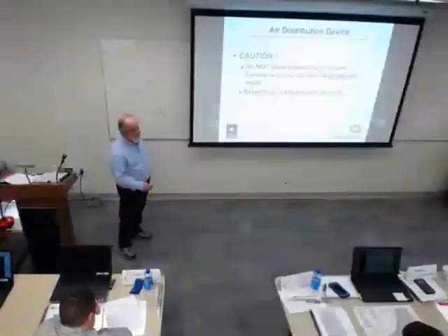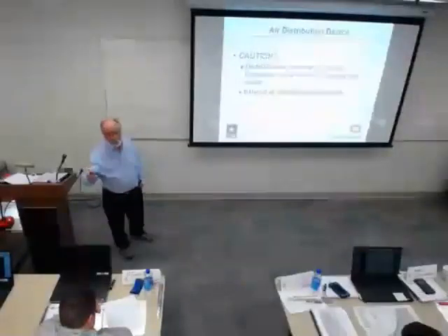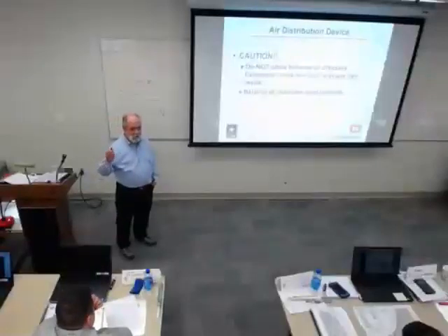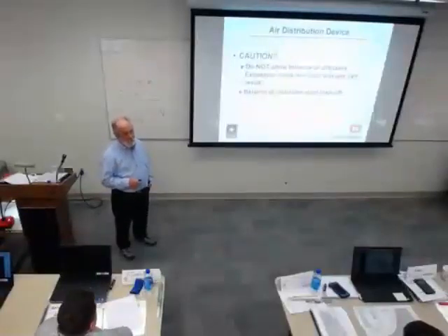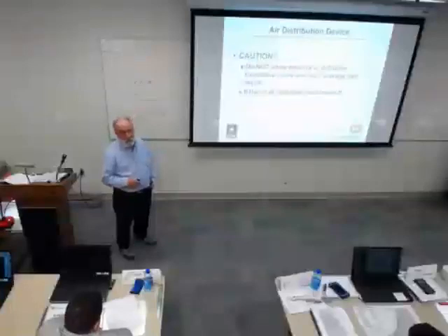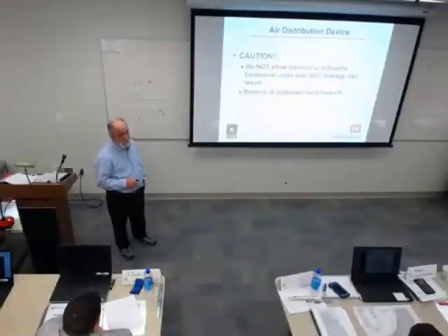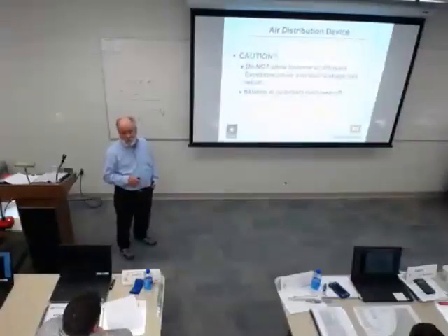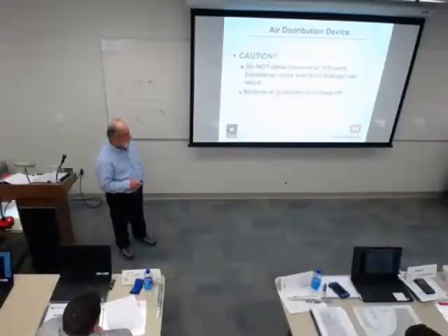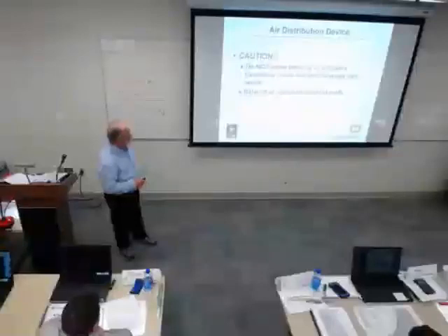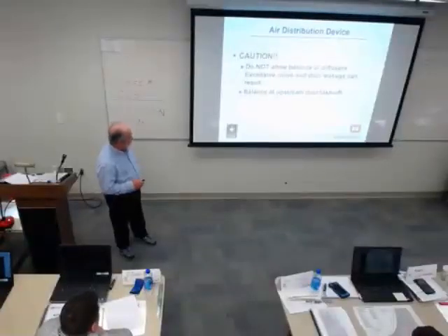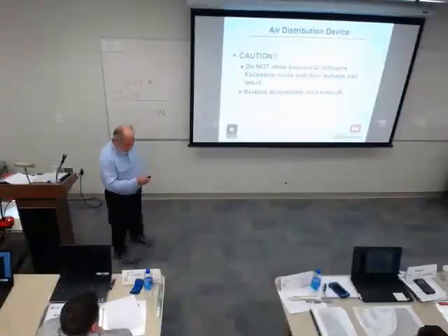You don't do it. I think we have a slide about that. You don't want to make the adjustment in the diffuser or grill. The reasons are legion, but two of them are it generates excess noise right there in your room, and they have a tendency to leak really badly. And they have a tendency to drift. None of those are what we call good. Okay, I just said that. Couldn't have a better slide if I made it myself.